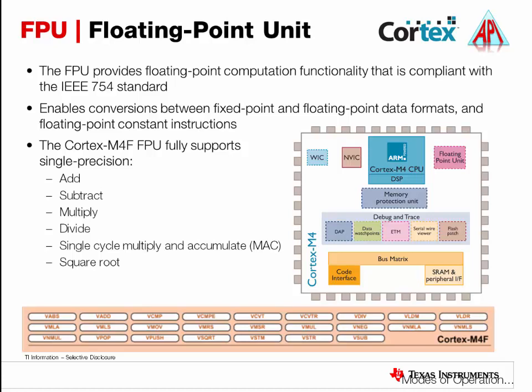Lastly, the floating point unit is another addition to the Cortex-M4F version chosen by the MSP432 family. The Cortex-M4F FPU fully supports single precision addition, subtraction, multiplication, divide, and square root, and so on and so forth. One thing to note is that FPU support is already enabled automatically in most of the compilers, so without a single click, you can already use floating point operations in your application with MSP432.